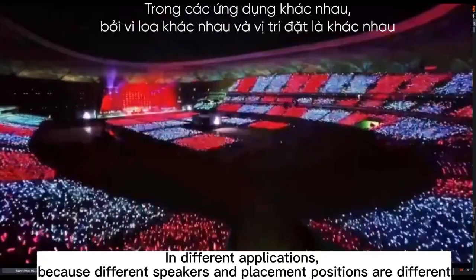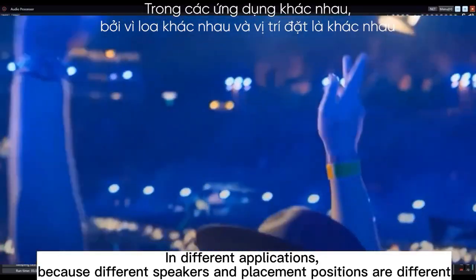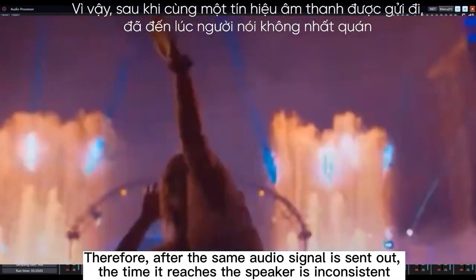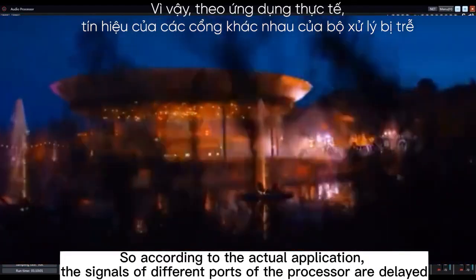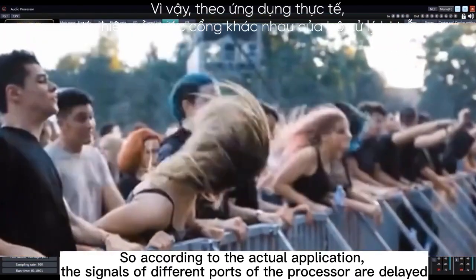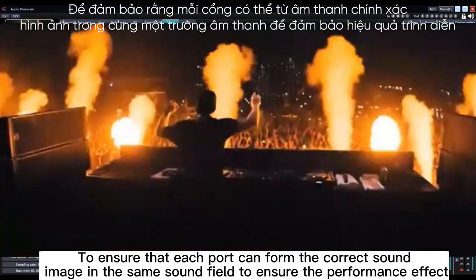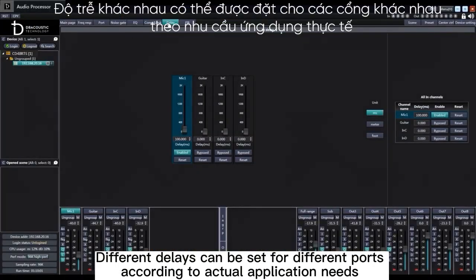Delay setting. This is delay setting in different applications. Because different speakers and placement positions are different, after the same audio signal is sent out, the time it reaches the speaker is inconsistent. So according to the actual application, the signals of different ports of the processor are delayed, to ensure that each port can form the correct sound image in the same sound field to ensure the performance effects. Different delays can be set for different ports, according to actual application needs.